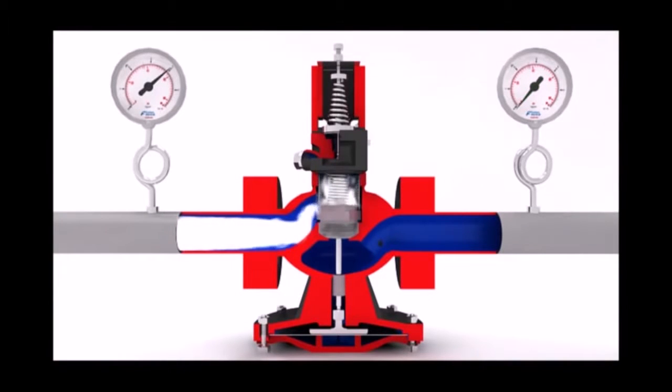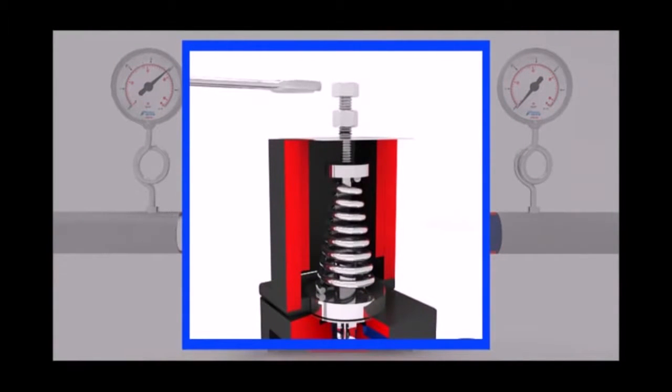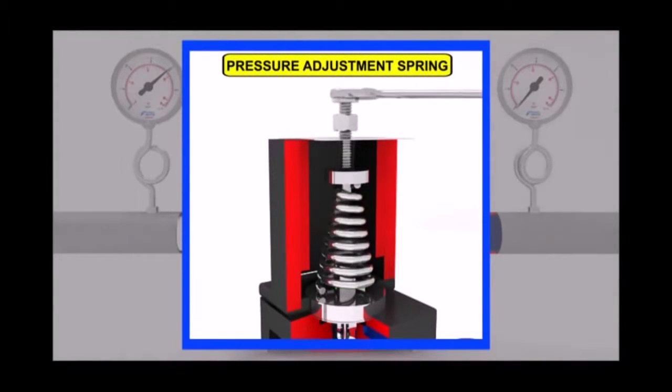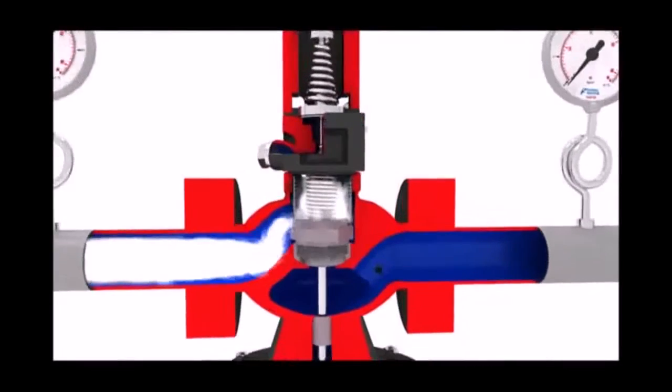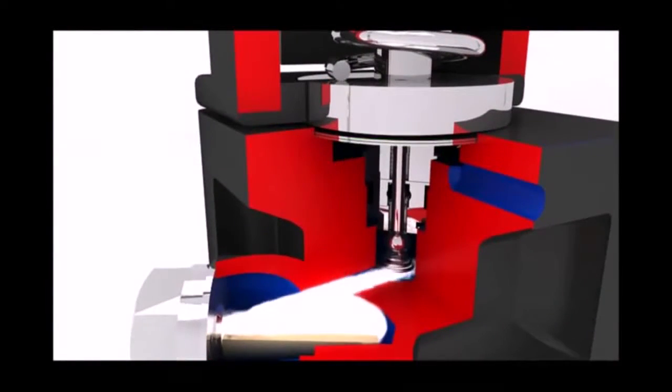and steam remains accumulated in main valve chamber. Tightening pressure adjustment bolt compresses the pressure adjustment spring. This results in deformation of pilot diaphragms, which in turn pushes the pilot valve plunger and SS ball against the spring located below, causing pilot valve to open.